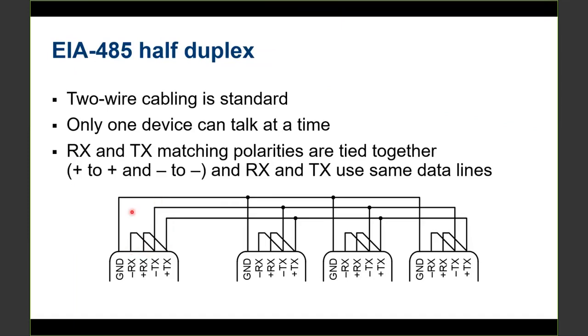Okay. Again, the half duplex timing is important, because you need to be switching your transmitters and receivers off. If you run into trouble, you can typically add some delays. Maybe you can key up your transmitter and then wait a certain amount of time before you transmit the data out across your comm path. And so there's a lot of settings that are associated with those timing, and they become more important when you're talking about half duplex communications.